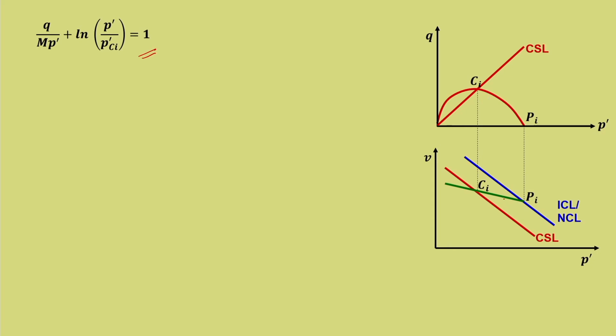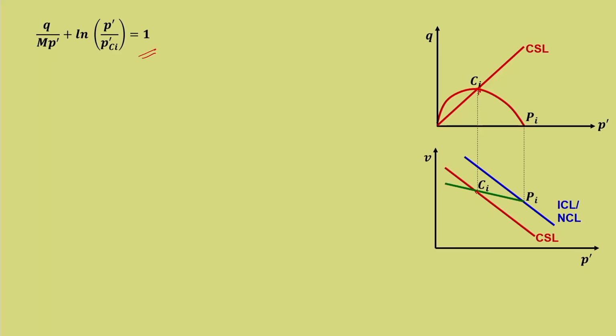In the last slide, we had not introduced this unloading line. Now, you can see that p' is here. This particular point Ci is nothing but the point of crossing where this unloading line is crossing the critical state line. I would not say that it is touching, it is only notional in this particular plot. It is the point where it is crossing. So, this particular point corresponds to Ci.